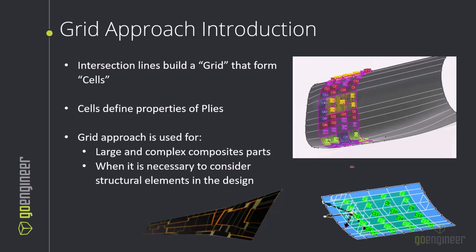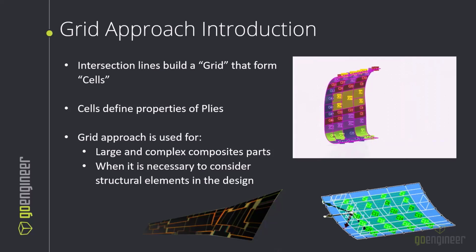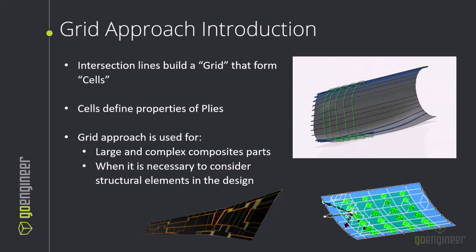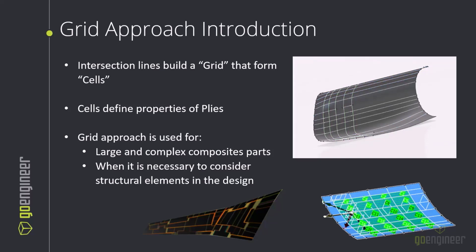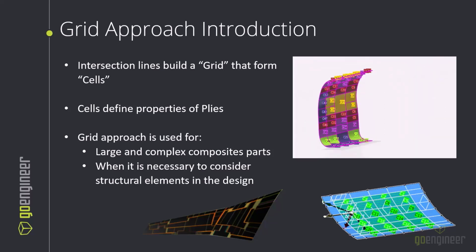And this is beneficial or a good best practice because we're taking the geometry that directly defines our structural or reference geometries and using them directly to build our composite definition. So in that case, if we were to move or modify any of these elements, they'll more easily propagate down to our composite definition and through to our sim as well as our manufacturing.